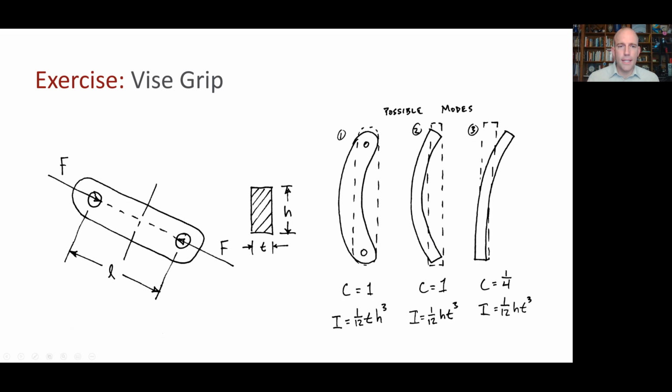Well, let's say we get to thinking, this looks like the thickness is a little smaller than the height. And the area moment of inertia would be smaller if we calculated it about this centroid. And that's true. And that's the second case. So let's say we still assume pinned, but now instead of buckling like this in the plane that we were presented, it's buckling like this out of plane. And while I is going to be smaller, that will result in a smaller critical force.